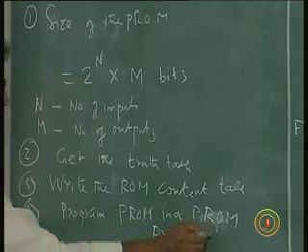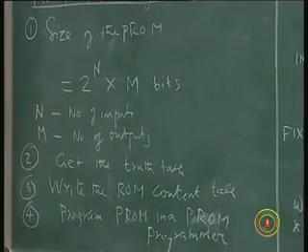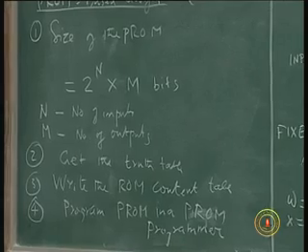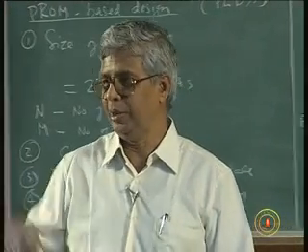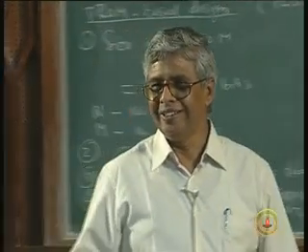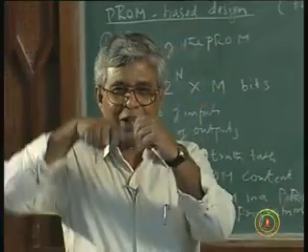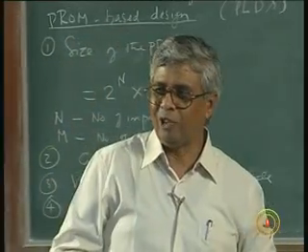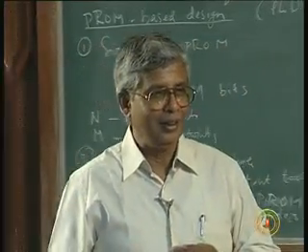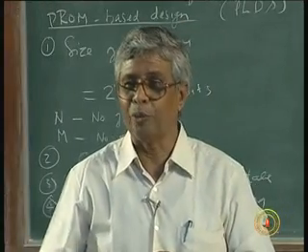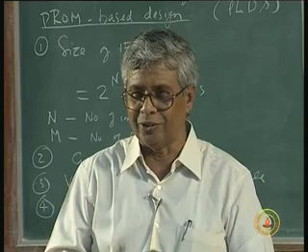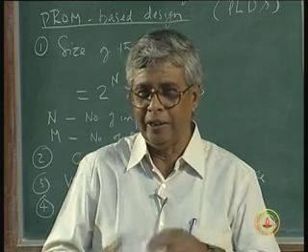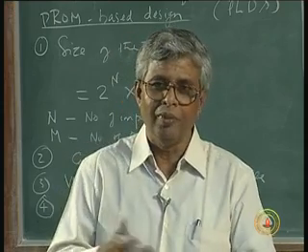Those who are industry people who have been doing this for a long time will say, burn the ROM. Have you burnt it? This is all pet jargon they use. Burning a ROM is putting the program in it. They are assuming there is a fuse and current is flowing and it is going up in flames and all. This is all imaginary. Putting a 0 or a 1 there is called programming, it is also called burning in colloquial terminology. Those designers who do it often say, have you burnt the ROM? That's what it is.